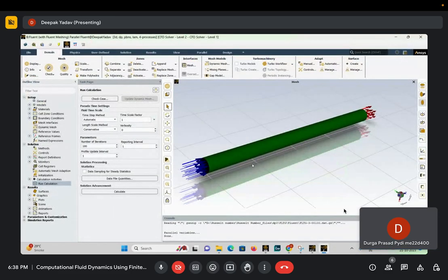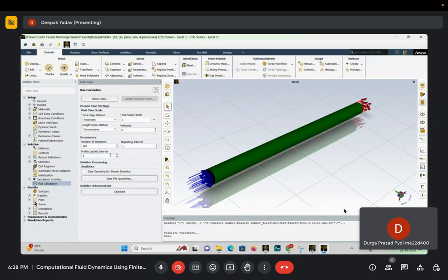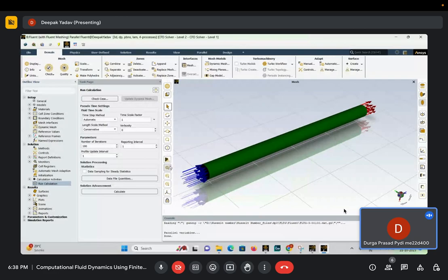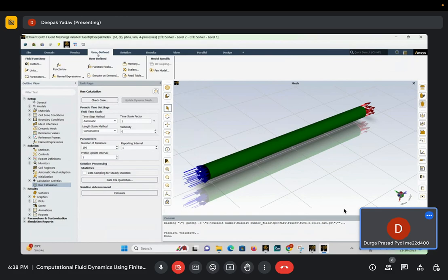Sir, this is my Fluent. So are you familiar with user-defined functions? I just have a basic idea of ANSYS Fluent. Yeah, it's a basic one, we'll just stick to the basics. You can go to the user-defined option, define some named expression, some new expression. No, the named expression, the top one below. You can define a function as well.